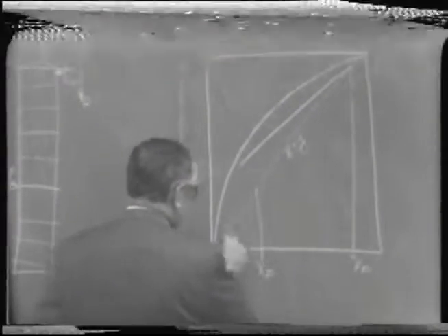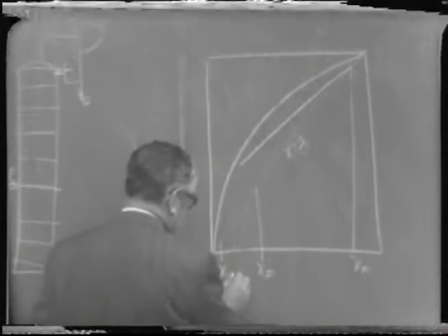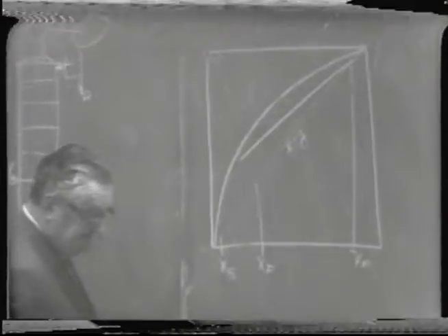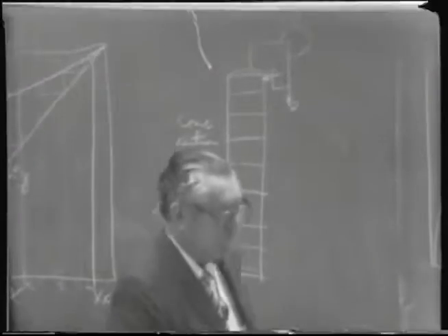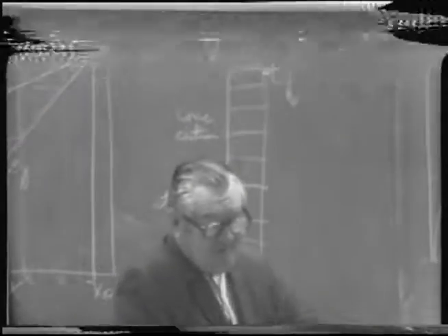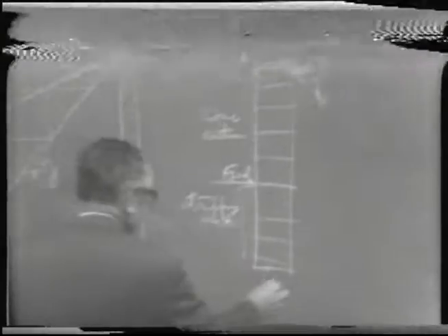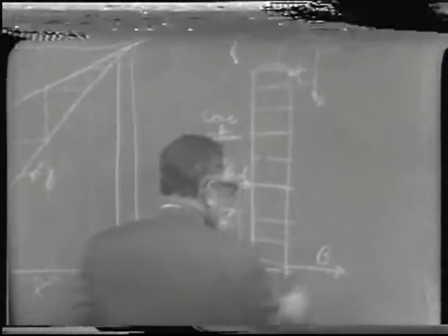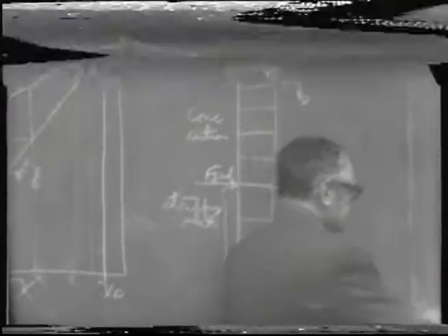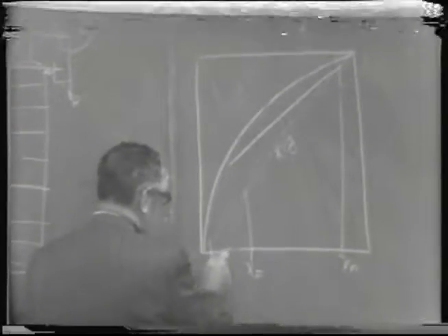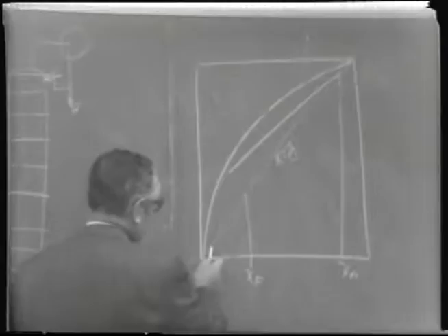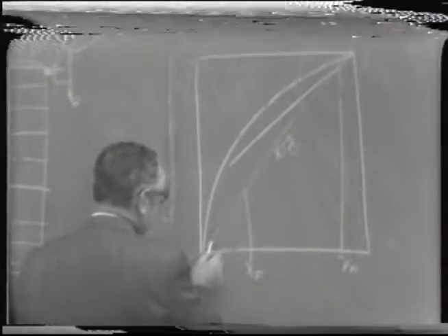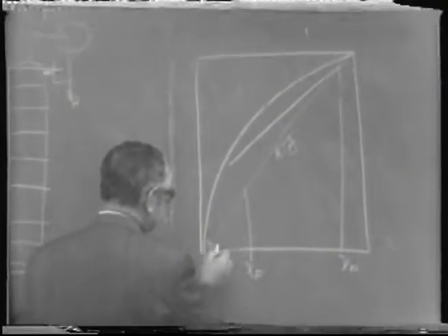And similarly for the stripping section, we have to have some measurable or theoretically measurable concentration of the volatile component in the bottoms product going out here, which schematically we'll represent by X sub B. And we'll find that there'll be an operating line which will have a slope greater than 1 for this section.